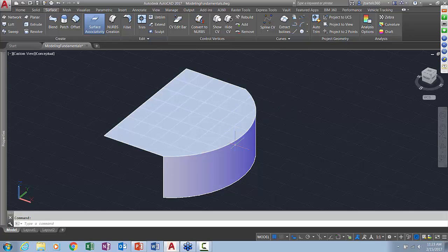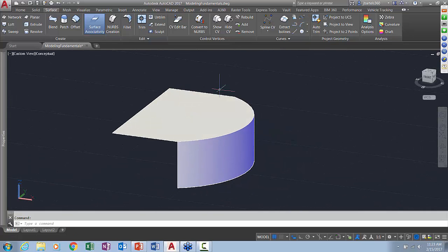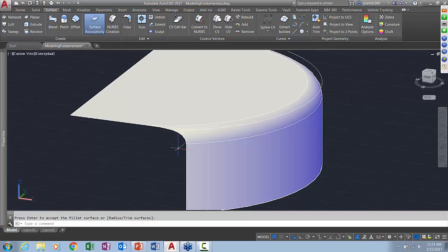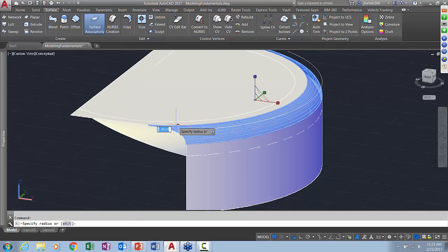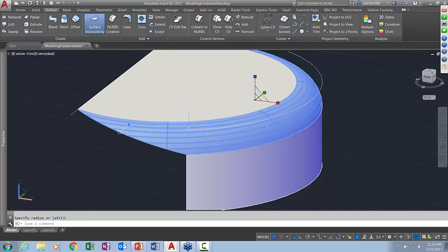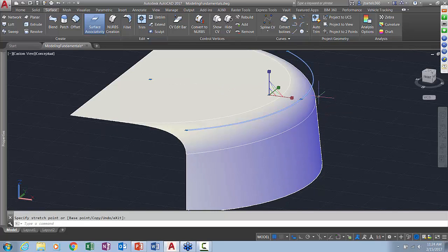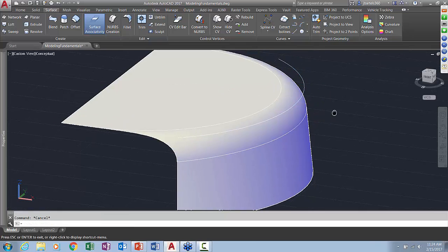Like I said, back in the day, these weren't the easiest to edit, but now we could do this. You may say, well, we can't fillet that. Well, now I can click those two edges, and I can set a radius, and I can apply that. I can click that radius after the fact and grab the grip. I can change that radius to something else. The nice thing, the surfaces of today will maintain a dynamic link to the geometry that created them.